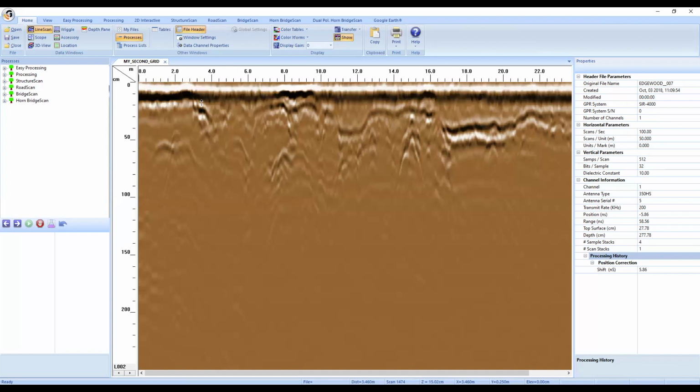For that reason, because we still have these tails, we would still want to perform a migration that migrates or collapses these tails, which will make the grave shafts look more defined and the grid look better when we're finally looking at it. So definitely worth performing a migration here, and seeing if we can collapse those tails and not have them point up or down. So we're going to want to just type in different dielectric constants. We can try doing a fit, but it might be easier to just type in numbers, hit apply, hit reset, and see if we can get those tails to collapse and not point up or down. Remember, if they point up, we need to move the dielectric constant up. If they point down after hitting apply, we need to move the dielectric constant down.